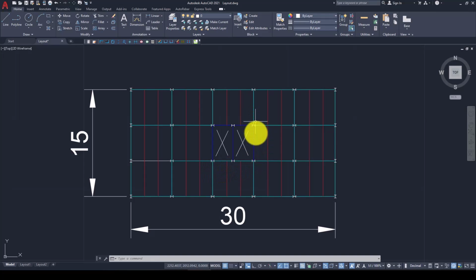And in the center, we will have one core area, one here and one this side, one here. In the previous ETABS tutorial, we added a shear wall. So now we want to create a resisting core area here. And instead of a shear wall, we want to use a bracing system. So the remaining part is a moment resisting steel frame.